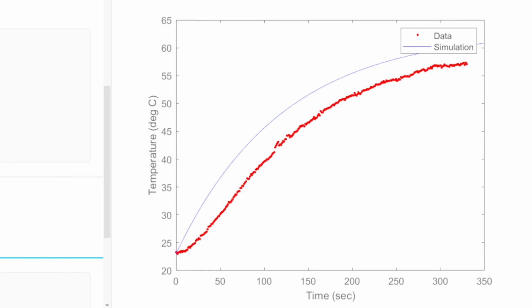This is one of the many points of a step test. As we look at the magnitude of our step input, from 0 to 50 for the heater for example, and the magnitude of our output, or the change in the temperature, we're able to develop heuristics that we'll use later on in control. This sums up our step test with the temperature control lab.